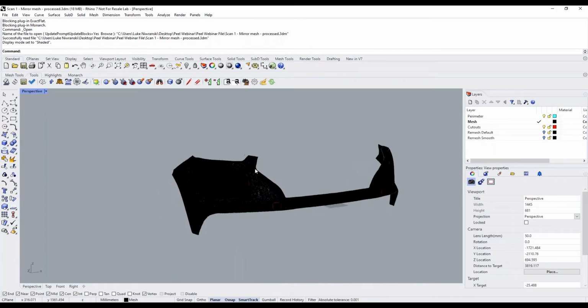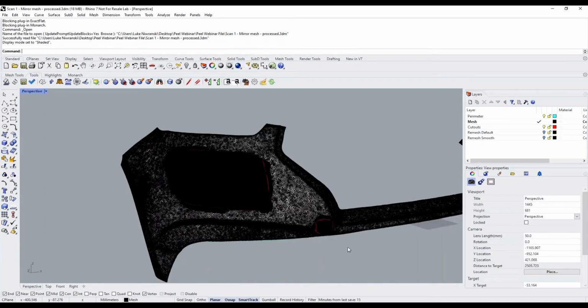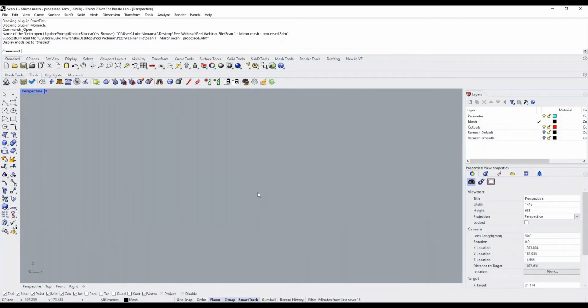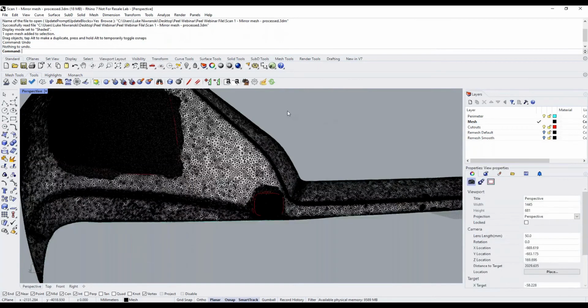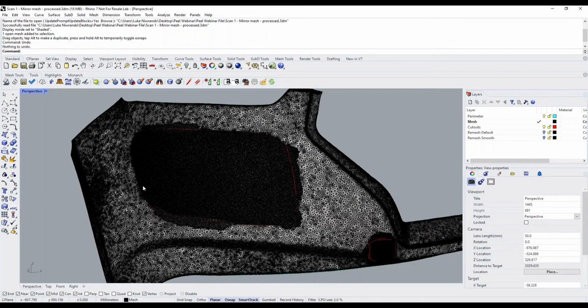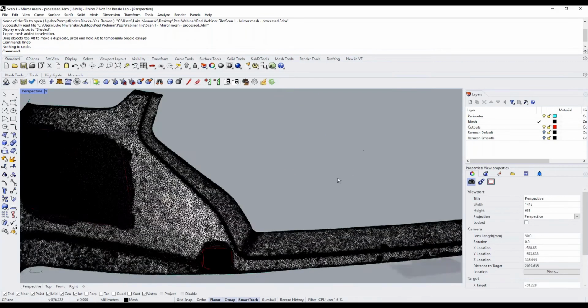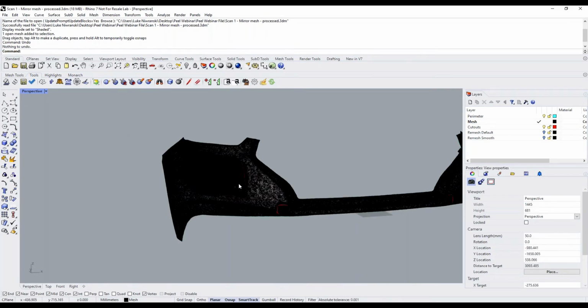I've taken a couple extra steps for this particular model. I've also filled in the headlight and I filled in the holes for where these cutouts were. But I've also created curve representations for where those boundaries were. I want to keep these curve representations because we do want these features to be on our pattern, but we don't want to be flattening those cutouts because they add unnecessary complexity to the flattening process. So instead, what we're going to do is we fill in the holes and then we trace the location of those cutouts on as curves afterwards. This is going to become a little more clear towards the end of the ExactFlat process when we can see the tracing process in operation.